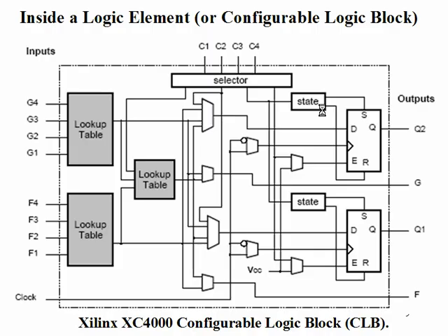Now this is what we have seen yesterday. Yesterday I drew a rough diagram. This is what you are seeing, from a Xilinx FPGA. The FPGA number is here. As I said yesterday, Xilinx calls this one a configurable logic block. So you will have lookup tables. Generally, most of today's FPGAs come with two 4-input lookup tables and one 2-input lookup table. Then they have a lot of multiplexers and all. They generally have one or two flip-flops, because when you want to implement sequential logic, they are required.